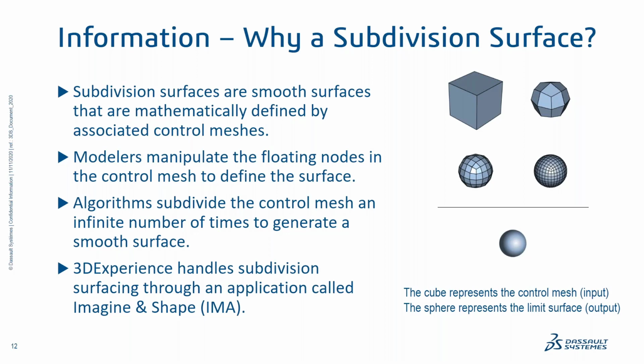What makes this nice is you have the ability to just directly pull on these nodes of this surface. So if you take a look at the square, for instance, those are the 4 nodes representing the sphere, virtual nodes that are floating out there, and you can take those 4 nodes and deform the sphere into any complex shape, basically, just by moving those 4 nodes around, right?